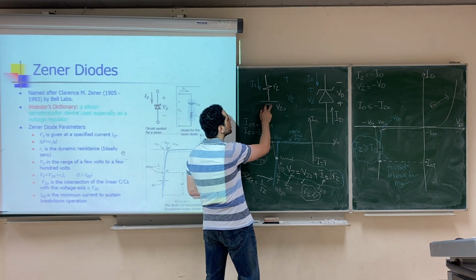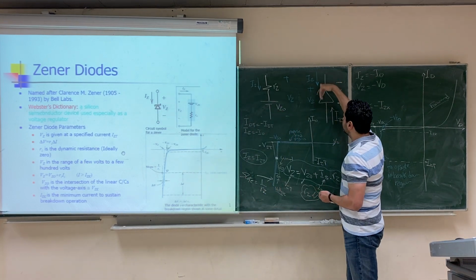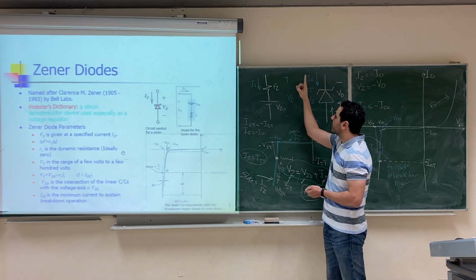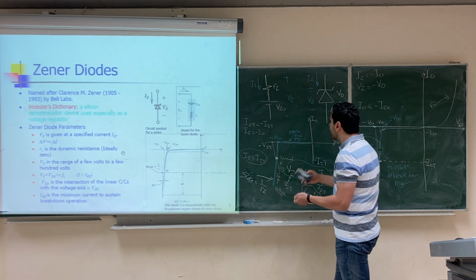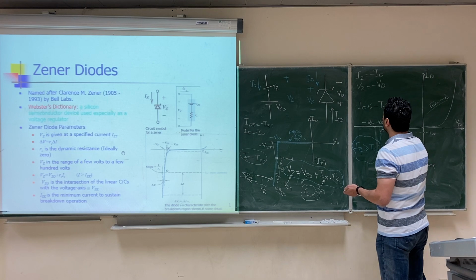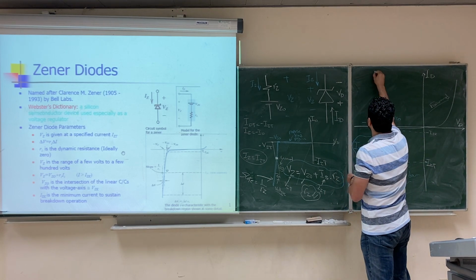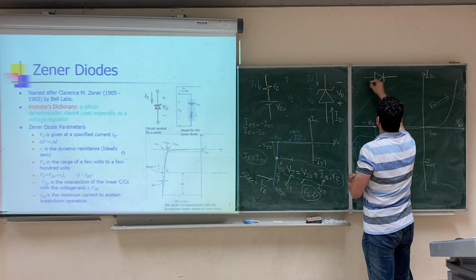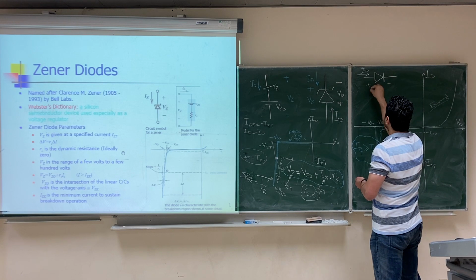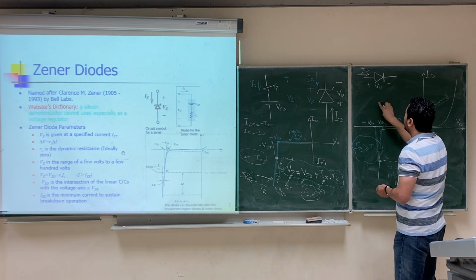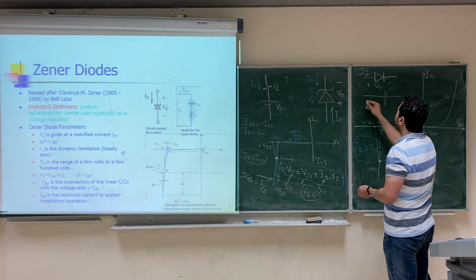Anyways, the model of the Zener diode, be careful, because the battery direction here, remember, is always opposite to the current. So if the current flows in the Zener in this direction, then the battery will be looking opposite to the current. In the regular diode, in the forward bias, when the current used to go in the regular direction, I diode, we used to model the diode using a battery, and the battery direction again was opposite to the current.